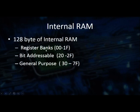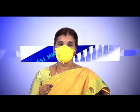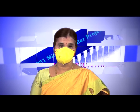Then 20 to 2F is used for bit addressable. That is the advantage of the microcontroller, which is both bit and byte addressable. If you want to get the data on a single bit, in the case of 8085 or any kind of microprocessor, we are outputting the signal on all 8 bits. But we are taking the signal from only 1 bit, the remaining power is wasted.